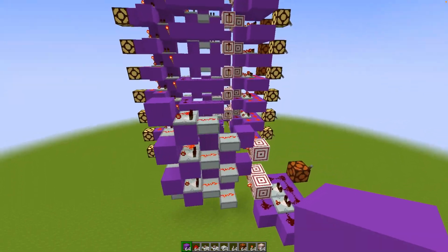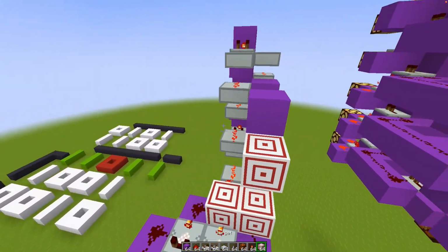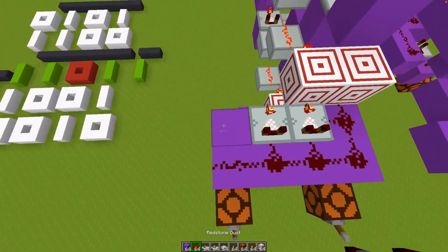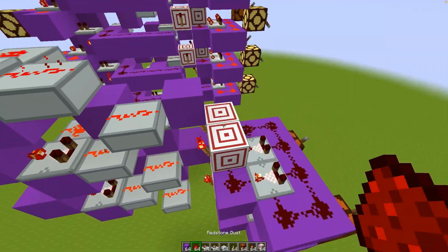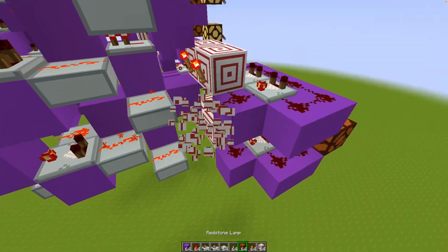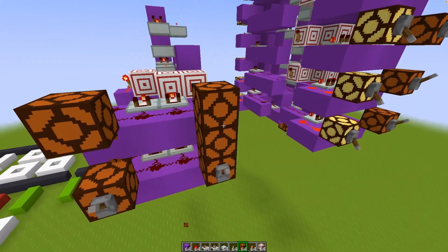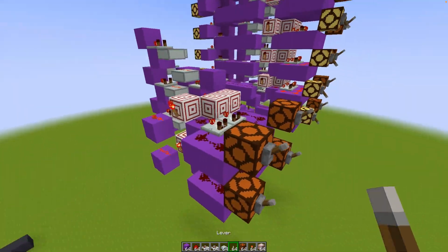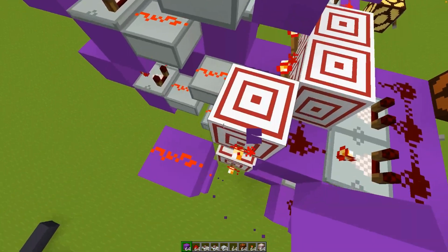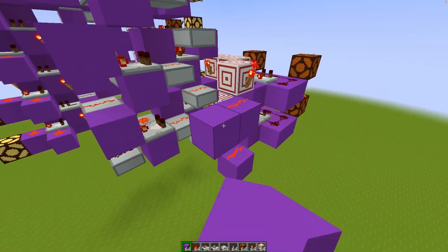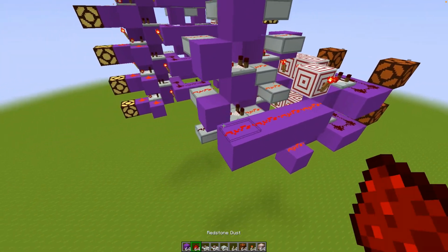So we already have calculated the carry, which is amazing. It's really that simple. We're going to be changing the bottommost module in a second, and I'll tell you why in a moment as well. But before we do that, let's just make the simple version. So we put our next input over here, and here we again take the XNOR instead of the XOR. And the reason why we do that is because of the next XOR.